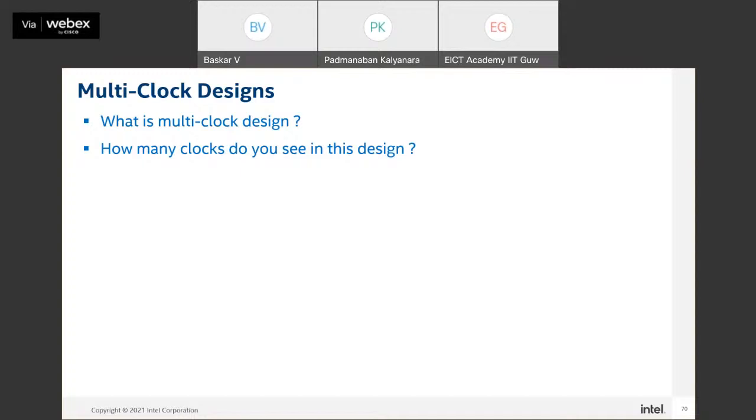Again, the external consumer may be operating at a different frequency. So how do we coordinate all these clock frequencies? How do we establish a proper handshake method so that whatever valid data we got from the external user application logic is properly handed over to the design, so that the design processes it correctly as per the functionality, then hands the processed results back to the external world?